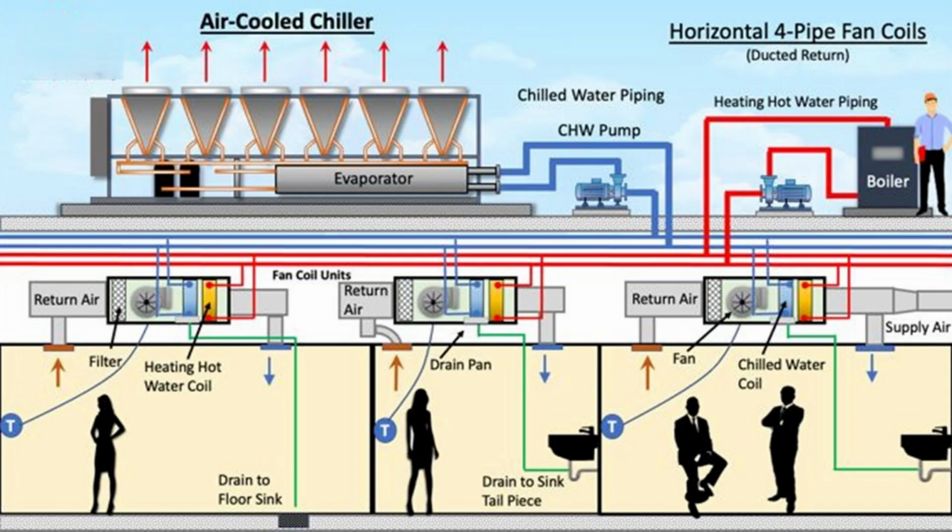Integration with building systems. A chiller plant doesn't operate in isolation. It integrates with airside systems, heat recovery loops, and sometimes even district heating. By coordinating temperature resets between air and water systems, buildings can maintain comfort at the lowest possible energy cost.